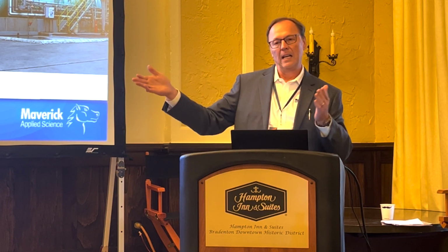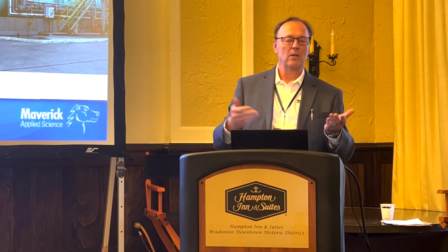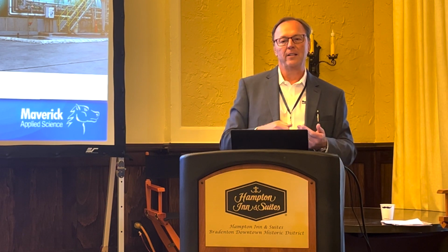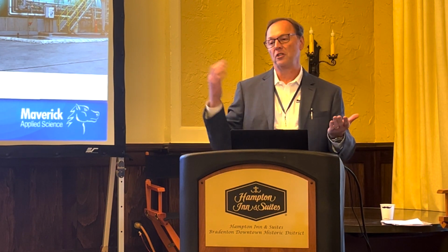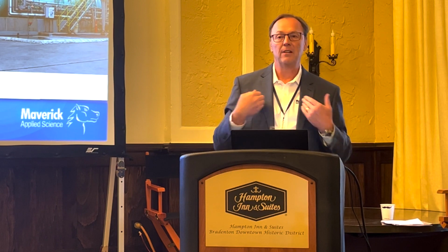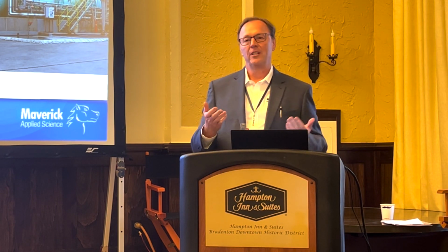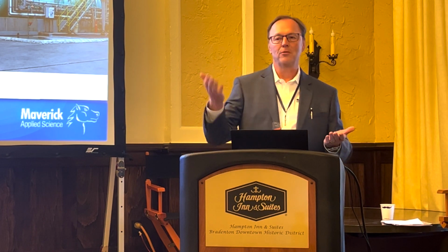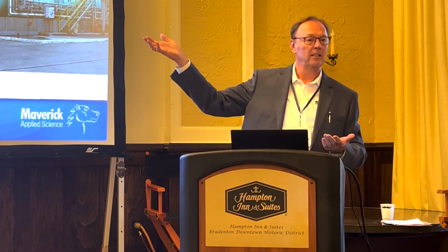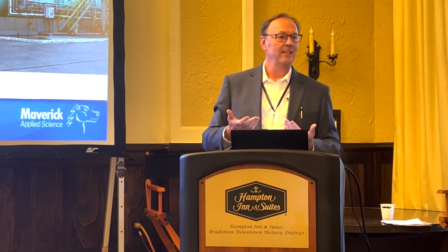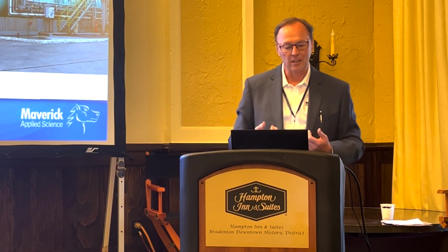So if you have a choice and three people come to you with these materials and they say polypro works for this just as good as PFA, well, if I'm the procurement guy, polypro sounds pretty good. But they don't tell you that this one is good for 7 years, this one's good for 10, and this one's good for 20. That's the reality of what happens a lot of times.